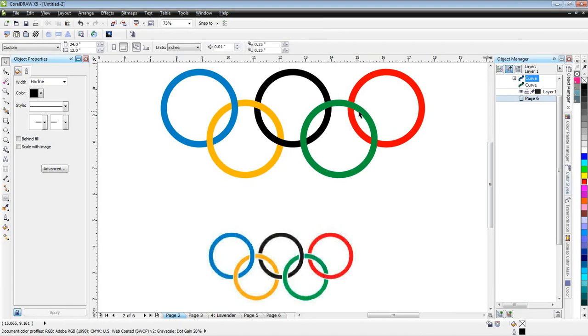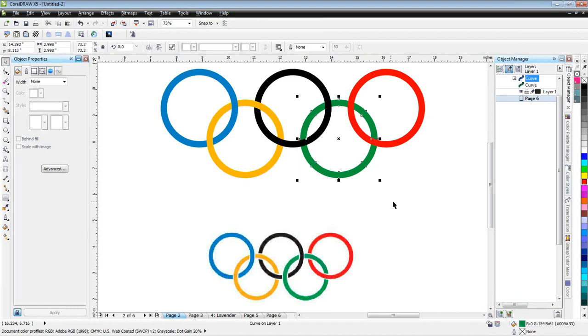And while we're waiting for some of that, I'll run through the green one here. So on the green one, I guess I want it under and over right there. So I have to have this on the bottom of the page, so I'll do Shift and Page down, put it to the bottom of the page. We'll copy it and paste it. And it needs to go under right there, so I need to erase that portion. So I'll erase right in here. And it needs to go under right here, so I'll erase that. And now I can select that portion, go to here, and we'll trim that. And we'll trim on this guy over here. And we'll trim that one. And I can delete my top one, and we're all set.